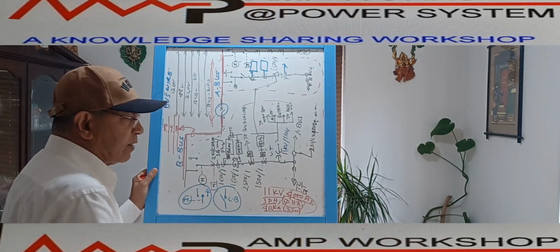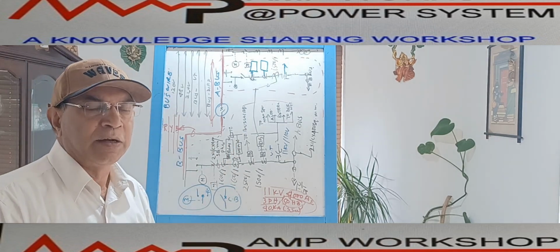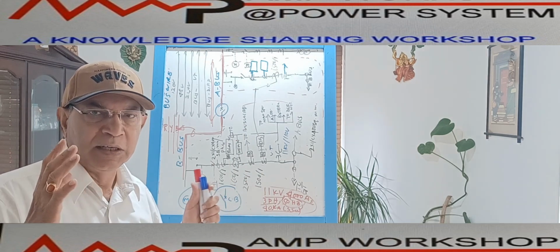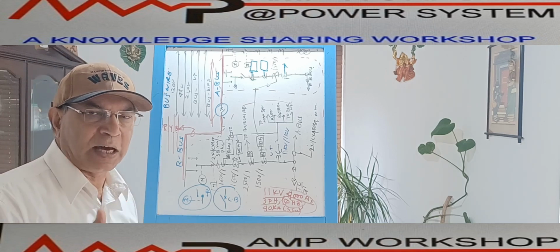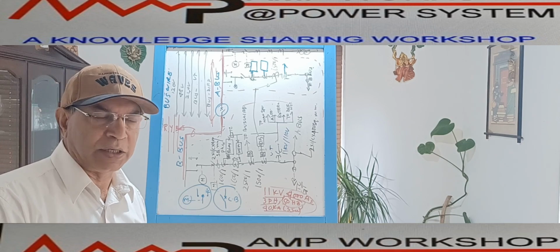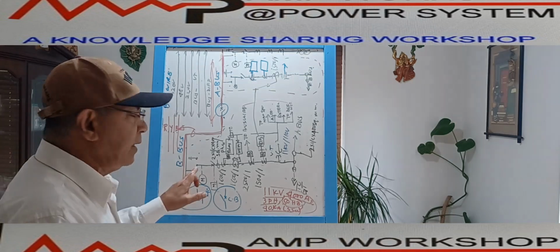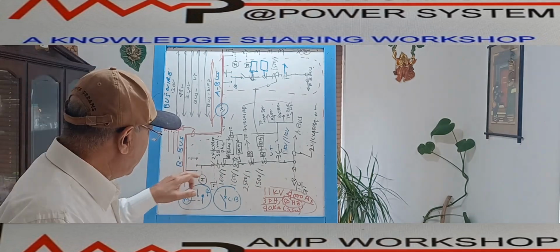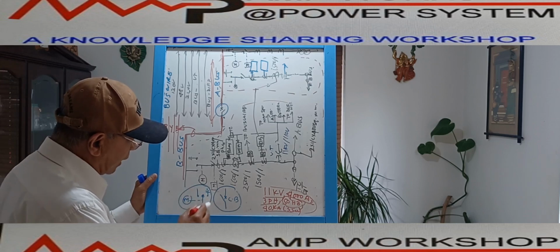So from here, first, what power equipment is required for this generator feeder? First we need the isolator. We are considering the SF6 fixed type switchgear. In the fixed type switchgear, to identify the service and test position, we have to put an isolator. So first we have the isolator connected from the bus bar. We are using an isolator cum earth switch over here. That is the symbol for the isolator cum earth switch.